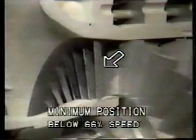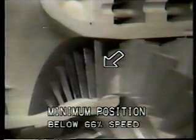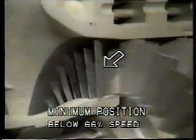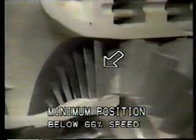There are two distinct positions for the variable vanes: the minimum open position and the maximum open position. When the engine is below 66% engine speed during startup, the variable vanes are in the minimum open position, allowing a reduced amount of air to flow through the engine.